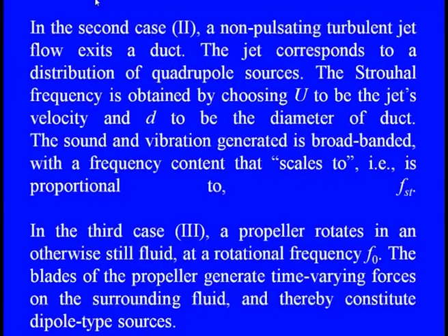Now in the third case which we are going to discuss, the propeller. The propeller is rotating, which means some extra features are added to the system. Then we have a clear rotational frequency as the propeller rotates at that frequency, and the blades of the propeller can immediately generate time-varying forces, which are responsible for creating a huge amount of vibration.